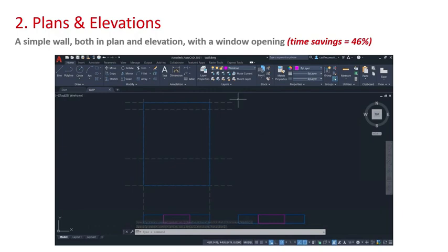I'll jump into the windows layer now, and what I'll utilize is a little bit of polar tracking and object snap tracking, which I'm sure you've all utilized before. So I'll hover over that corner there, come up to the intersection with the construction line, and again hover over the other corner in the plan view and come up to the other construction line. There's the intersection, and there's my window representation in 2D. So that's all flat, and I've had to draft all of that manually.